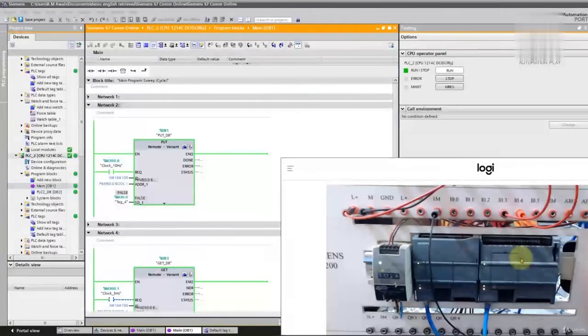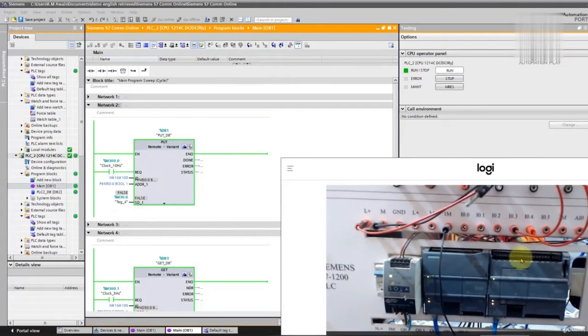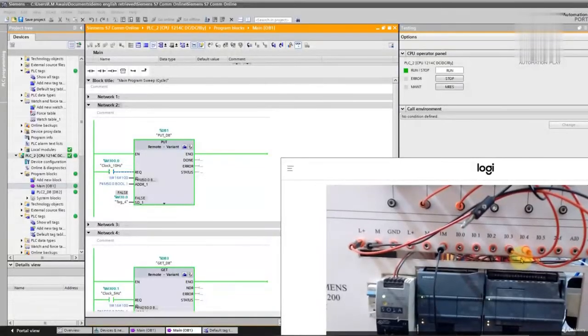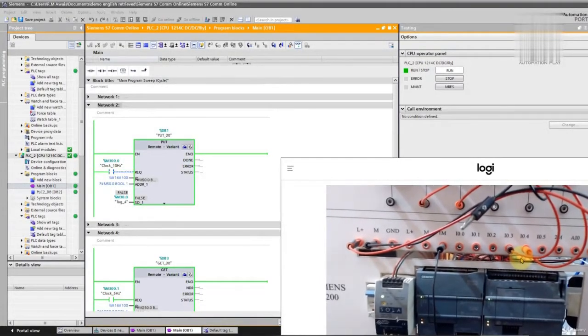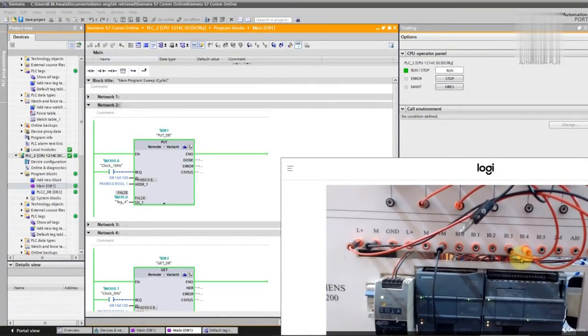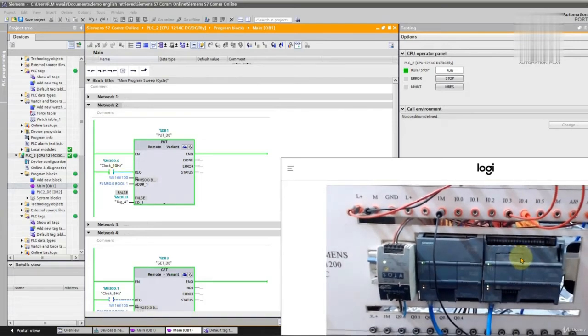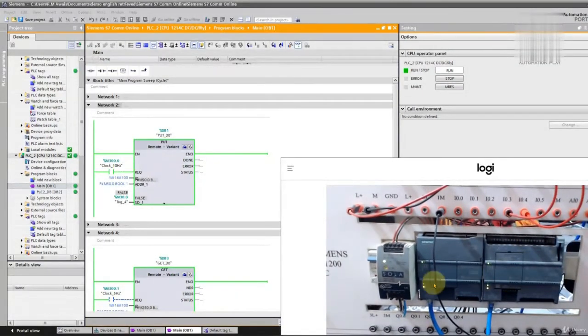So if I press my push button of PLC 1 from over here, my output in PLC 2 is getting on from the input of push button 1, like that. So this is the task that we have to achieve in this section. We have to establish Profinet communication or Ethernet communication between these two PLCs. We are going to use get put instructions and further instructions as well.